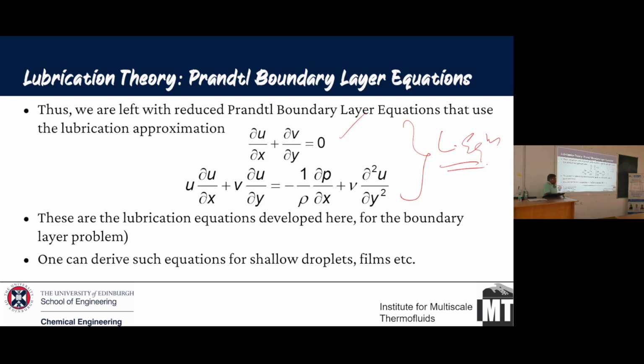During the stability analysis of the evaporating droplet, what base state are you taking, because you are saying the phase change is constant? Yeah. So that's a good question. When we consider evaporating systems where the base state is not constant, there are two methods we use. One uses severe assumptions. The first is called a quasi-steady state stability analysis. We freeze the system in time. So we do the simulation, and we freeze it each time.